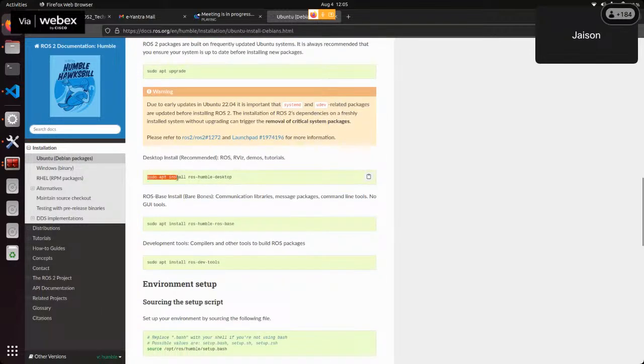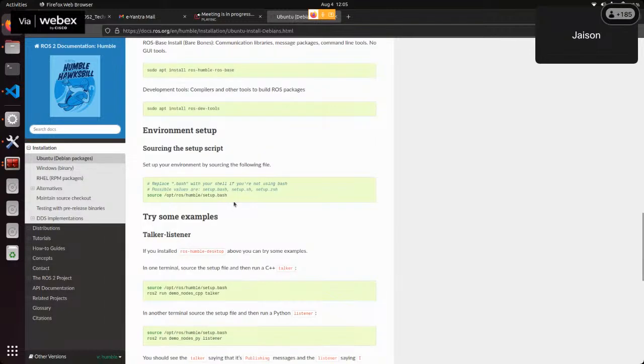After going through the steps, you just have to type sudo apt install ros-humble-desktop, and it will install all the basic necessities, even turtlesim and the basic features needed in ROS2 communication, to create packages, and to install other packages. Everything will be installed. And this is where I told you that in the bashrc this thing is to be sourced. After installation, the setup.bash contains the list of where the packages are, what the nodes are, and what the contents inside particular packages are.